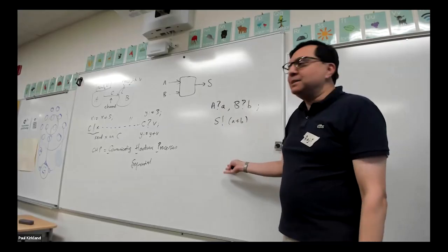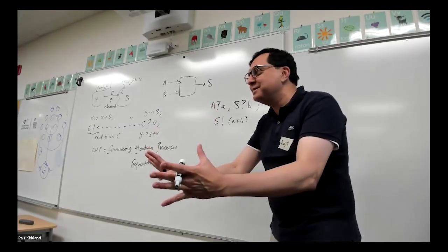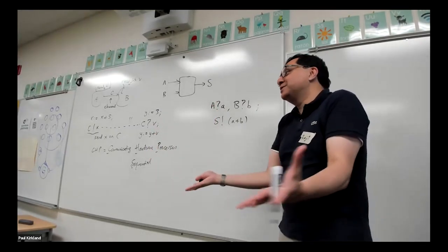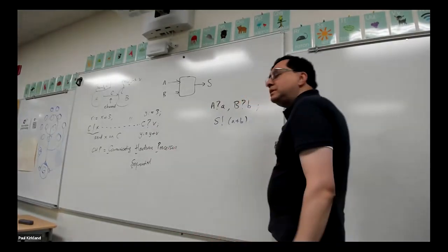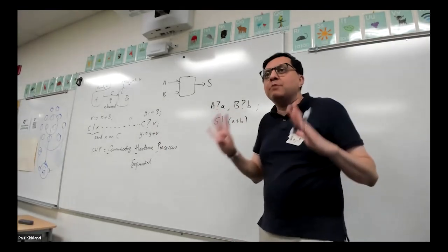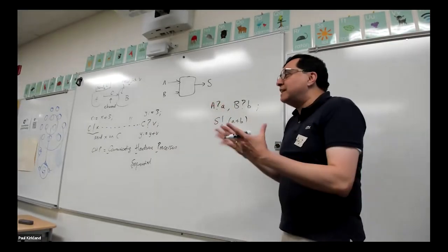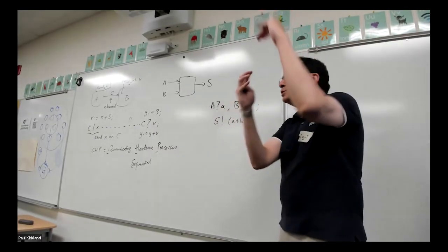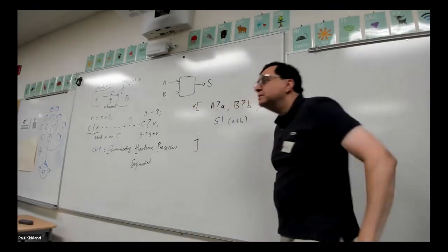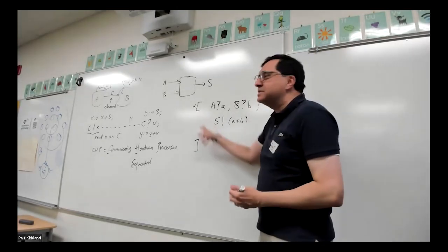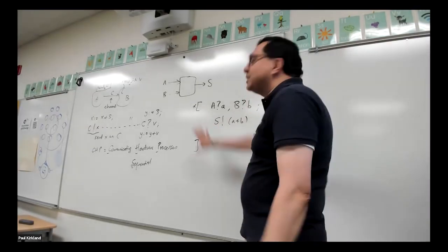But if I wrote this program, it does this and then terminates. There's nothing else to do. Well, with one entertaining exception, your hardware normally doesn't terminate. What does hardware terminating even mean? I'd have to power cycle the system. So typically hardware doesn't terminate. The semicolon is sequential, just like in a normal software programming language. So I normally wrap this in an infinite loop. Almost every chip, all the little pieces, look like an infinite loop where you do something. The syntax we use for the infinite loop comes from a paper from the 1960s by Dijkstra, his guarded command language.